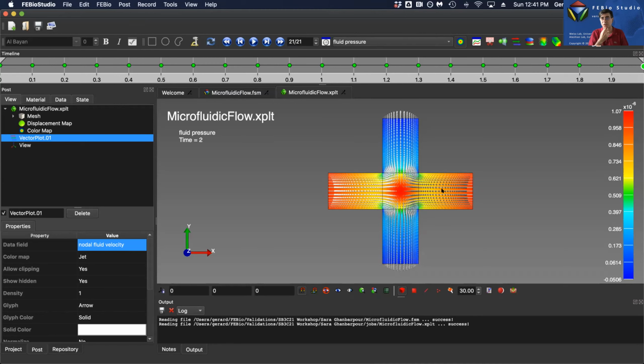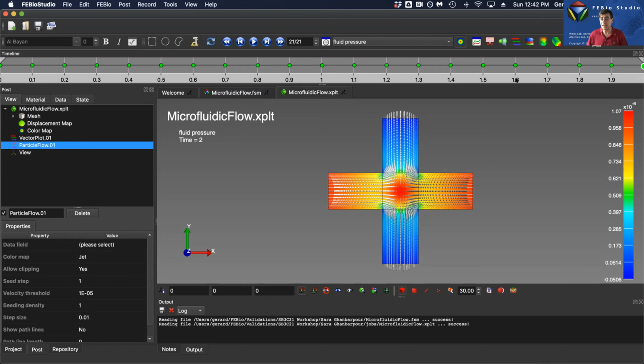That's an extremely low diffusivity, which means that the Peclet number is very high, which means that the particle is actually moving at the velocity of the fluid. So you actually don't need to do the solute transport analysis. So this is a fluid mechanics demonstration. Let's use this vector field to track how a fluid particle would move. And in reality, if a fluid particle moves at the velocity of the fluid, your sphere is going to move exactly the same way.